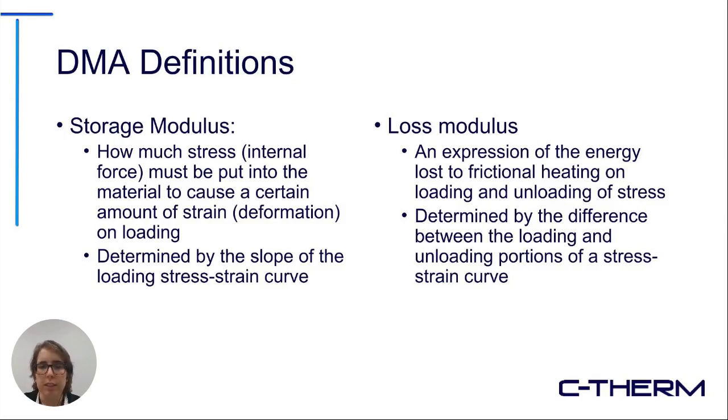The storage modulus is kind of analogous to another property that some folks might be aware of called the Young's modulus. The difference between the two is that the Young's modulus is basically what you measure when you're pulling the material apart and applying the stress in a pulling motion, whereas the storage modulus is when you're applying a compressive force.